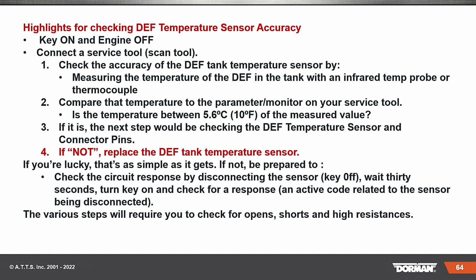I didn't go through the whole flow here. If you're lucky, that's as simple as it gets. If not, you guys know, I'm preaching to the choir. You're going to have to go further, aren't you? For example, check the circuit response, disconnect the sensor. You're going to watch it on your scan tool. What's the response, and so on?